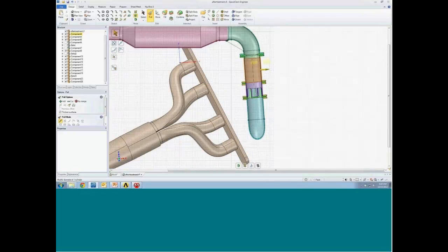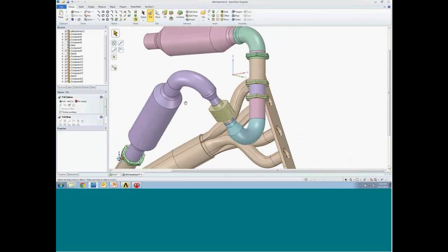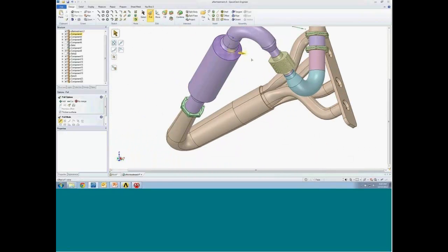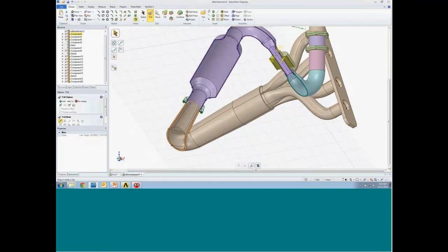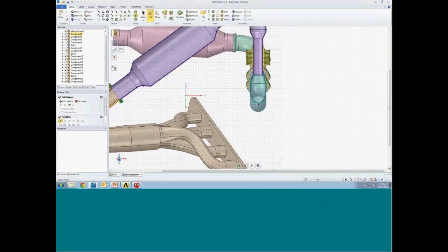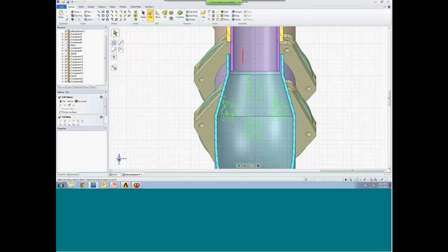Now, again, I know ahead of time there's another opening on this body. Let's go ahead and find it. I think it is right over here. Again, I'll go into, select an axis and go into a cross-section mode. And I'll draw on the screen for a moment. You can clearly see where gases could escape out. So let's take care of that.